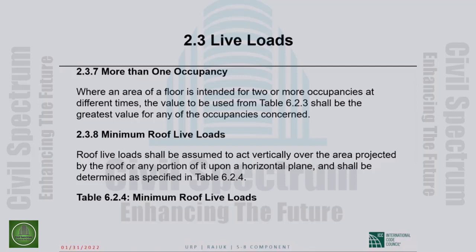Minimum roof live loads. So floor live load is L, roof live load is L sub R. Roof live loads shall be assumed to act vertically over the area projected by the roof or any portion of it upon a horizontal plane, like all live loads, and shall be determined as specified in table 6.2.4.